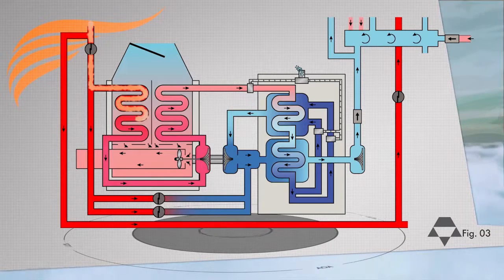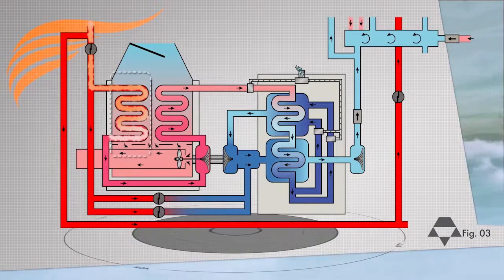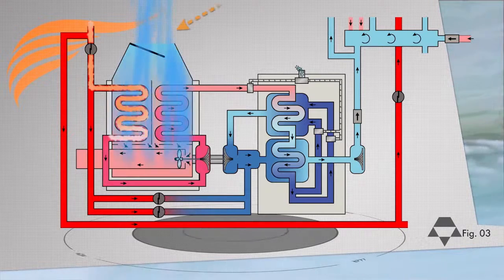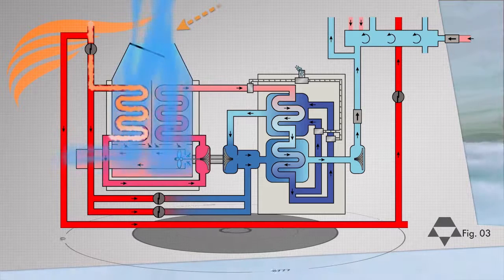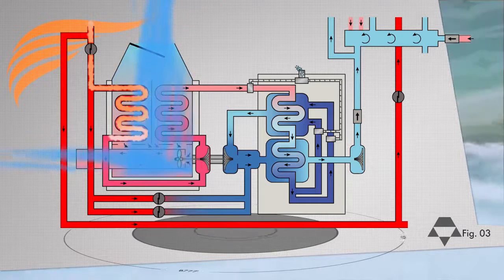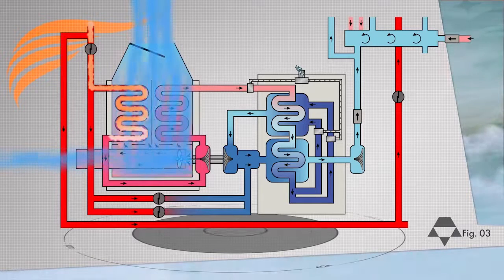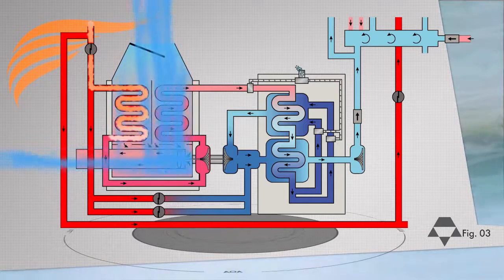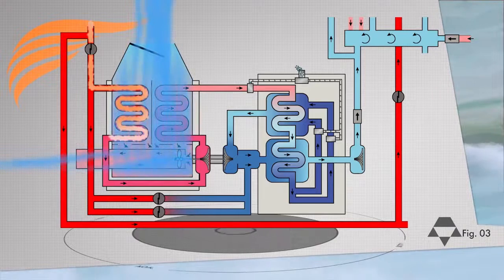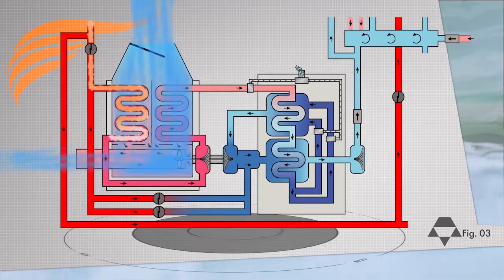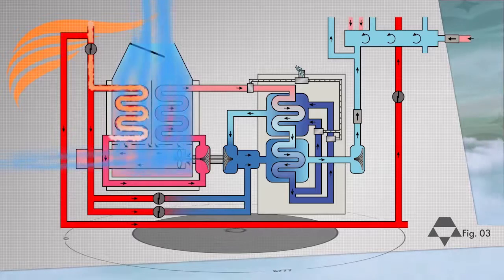So first, bleed air from the pneumatic system is run through a primary heat exchanger, where it's put into contact with ram air in order to lower the bleed air's temperature. A quick refresh. Remember that bleed air is very hot, highly pressurized compressed air that's extracted from the high-pressure compressor stages of the engines in order to feed the aircraft with pneumatic power.